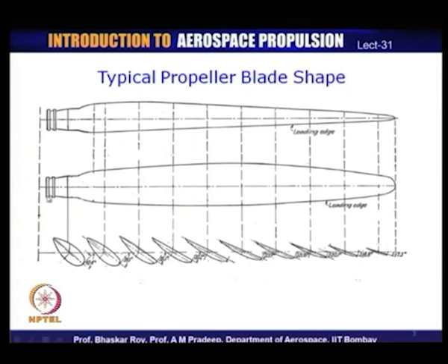And as a result of this cantilever arrangement of the propeller holding, the entire propeller load, the aerodynamic load, the lift and the thrust that we have talked about, created by the propeller itself, has to be borne at the root of the propeller, and that is where all the stresses, strains and the moments are actually finally felt.